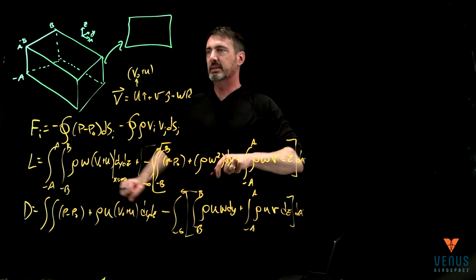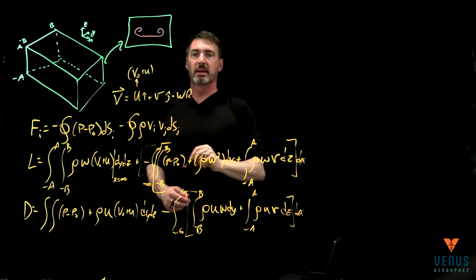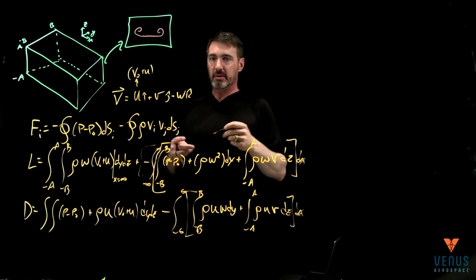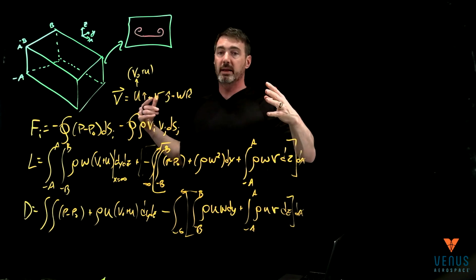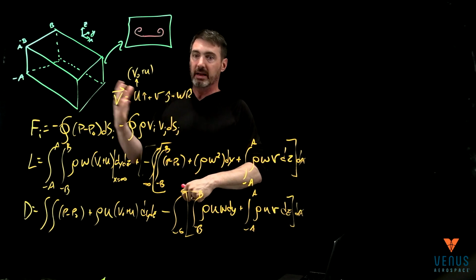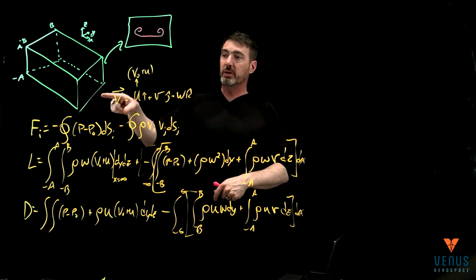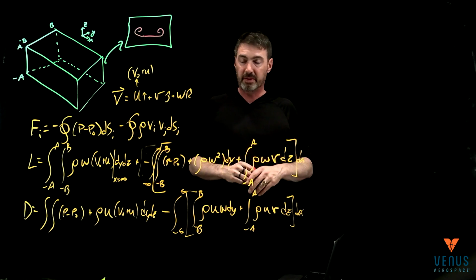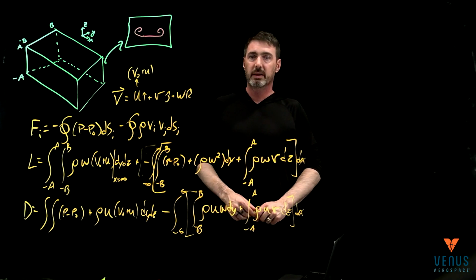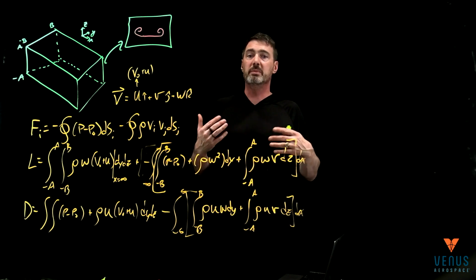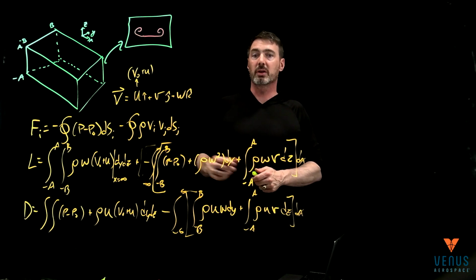That's why we're doing this, is we will see that there's sort of a vortex that's kind of caught in the plane. So the idea now is that this plane is far enough back, and A's and B's are chosen wide enough that you've captured the entirety of this thing, and it's so far back that basically these vortex loops are perpendicular to this back plane. So there's no extra forces happening here. It's kind of steady, which is not true in viscous. It would always be decaying if it's viscous. But this is so far an inviscid approximation, and we're still going to learn a ton from this.